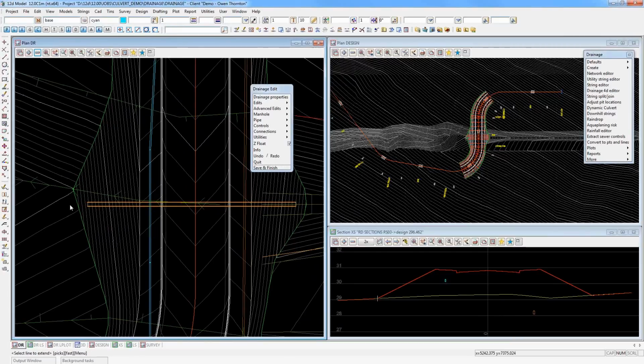Most culverts roughly look like this in plan. They don't typically extend all the way to the bottom of the batter slope, because there's typically a head wall built in place there that ties in nicely to the batter slope and gets the apron, or the bottom of the head wall, fitting snugly with the bottom of the channel at either end. Okay, now that's not been placed in lengthwise with precision. Certainly the alignment of this culvert is now perfectly perpendicular with our road center line, but the length of that culvert we've only just put in very roughly.